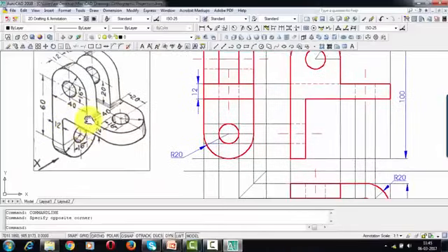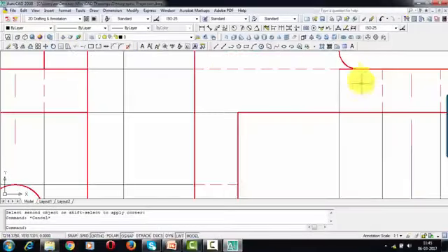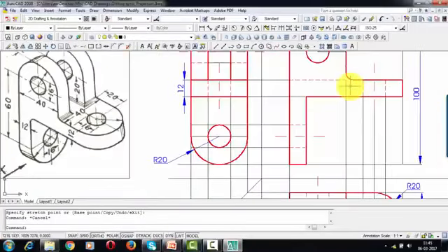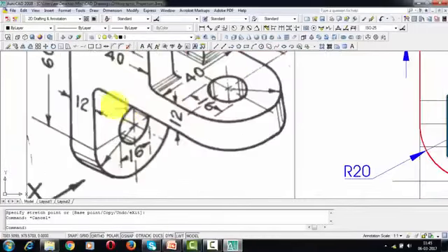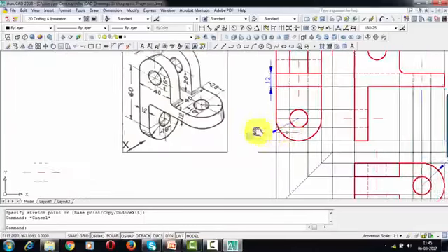Okay, now what we're going to do is make a fillet of this. Let us try to do that. There you go. Alright, and let me slightly clip this portion. Perfect. Now this portion in fact also appears as a fillet. So what I've done is I've made a small quarter arc, or a quarter circle, of radius 5 millimeters. That's exactly what we've done.